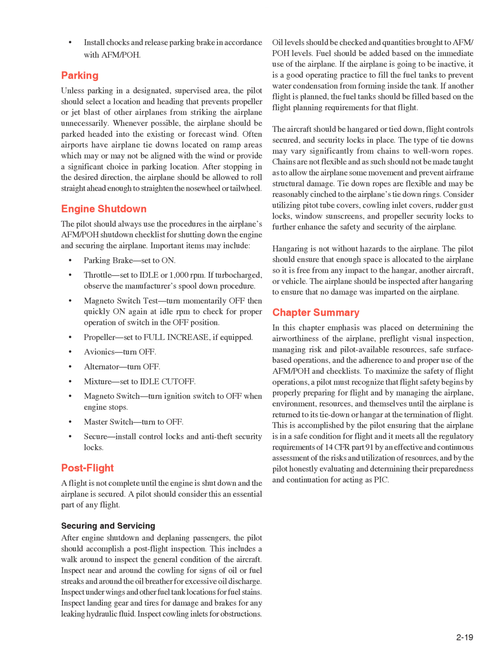Avionics, turn off. Alternator, turn off. Mixture, set to idle cutoff. Magneto switch, turn ignition switch to off when engine stops. Master switch, turn to off. Secure, install control locks and anti-theft security locks.